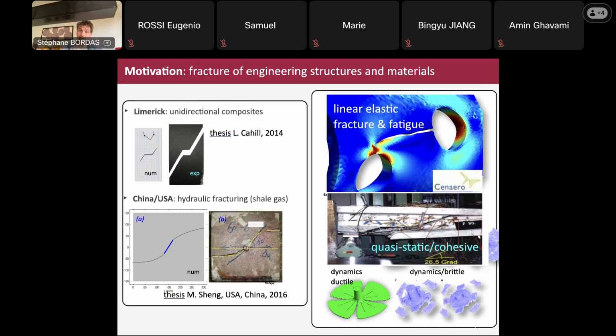And in order to simulate all of that, all these examples, including the fracture and brittle fracture that you see at the bottom right, you start with a continuum. This is a Taylor bar hitting a wall at large velocities. This is a way that you measure the ductility of a material. This is very interesting because you see petals that are forming, and the number of petals indicates the ability of your method to reproduce reality. So if you're able to reproduce the fact that you have here 4 petals and 2 minor cracks per petal, well, that's going to show that your method is able to reproduce that. And using computations, we are able to do that.